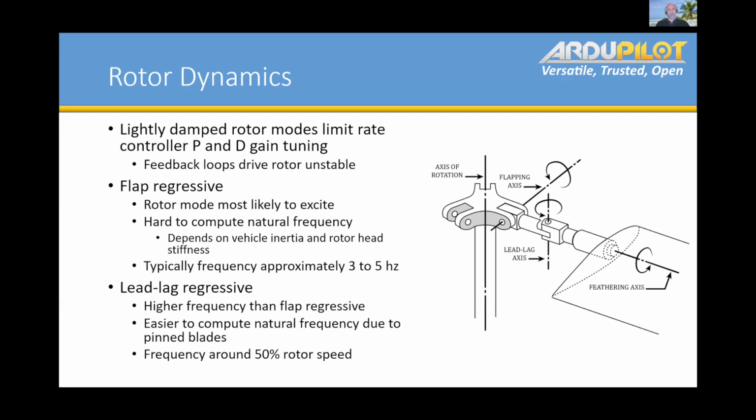And so I was actually able to notch that frequency and drive my P gain up to something where I could actually fly the aircraft just on P gain alone. That was pretty interesting, but that's the only one I've been able to do that with. On all these other helicopters that I've experienced and tried to help folks tune, this 3 hertz in the pitch axis tends to kill you. You just can't get away from that, and it really affects the dynamics of the helicopter.